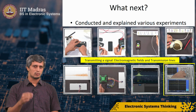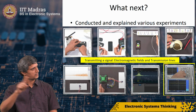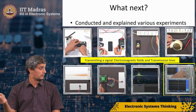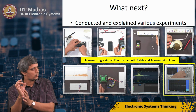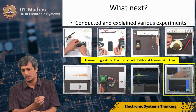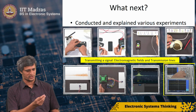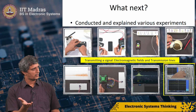So you're saying that the moment you have current flowing in some loop here, you can have a magnetic field that is remotely affecting a circuit nearby. And imagine 8 billion transistors in an area of 25 mm by 25 mm. Then you're talking of very close circuits, so even the 1 by r square effect is not going to be there. You're going to have a serious interference. So that is what we are going to cover in this course.